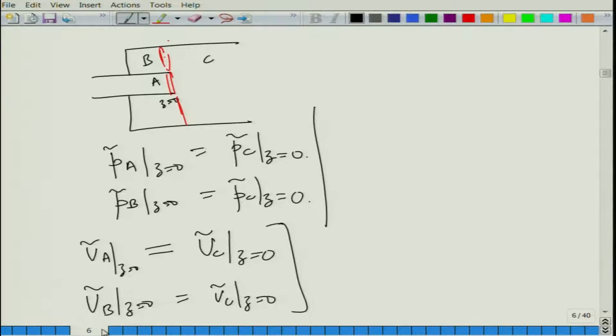We will do some sort of mode matching, exploiting again and again the 3-dimensional analytical approach, wherever you have a mode matching or a piston driven model or a Green's function model, wherever one has to incorporate the 3-dimensional effects without resorting to a full 3D analysis, without completely discretizing the 3D continua into finite elements, rather just discretizing the work on the 2-dimensional problems.